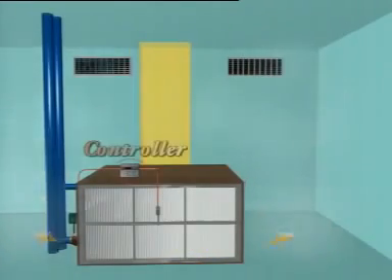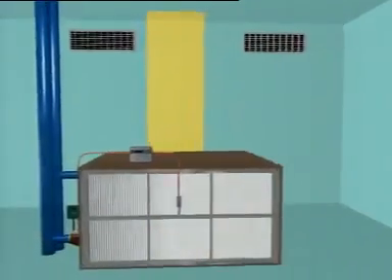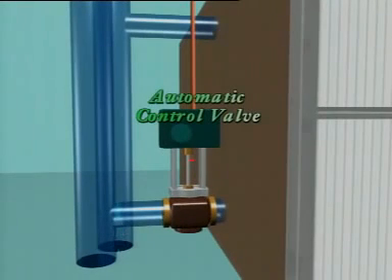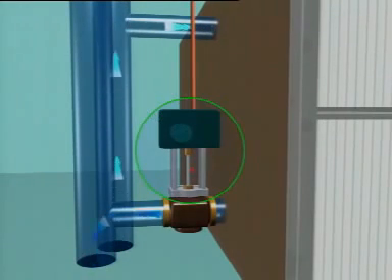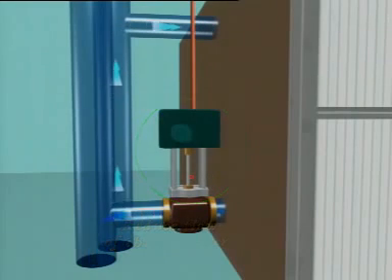It sends signals to the controller, which compares the measured temperature with a set point and controls the automatic valve to regulate chilled water flow through the cooling coil. Because of the drop in temperature, the automatic valve is instructed to throttle, thus reducing the flow of chilled water to the cooling coil.